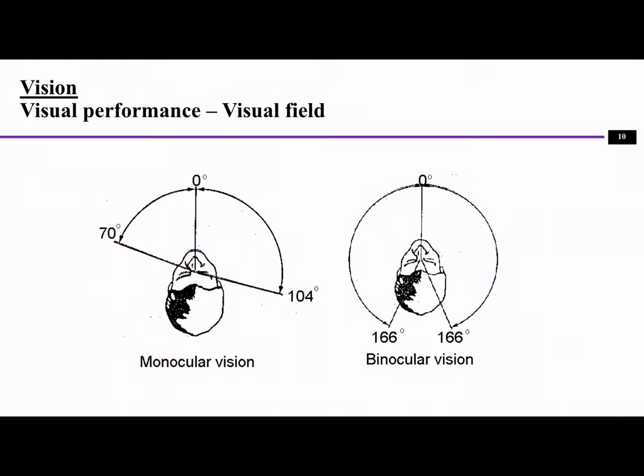And when we are doing a visual search, especially in some inspection of the parts, there are a lot of factors we want to look at. For example, visual acuity, color vision, and also discriminability, and also memory standards and decision criteria you want to take care of when you are having some kind of visual inspection of the products.